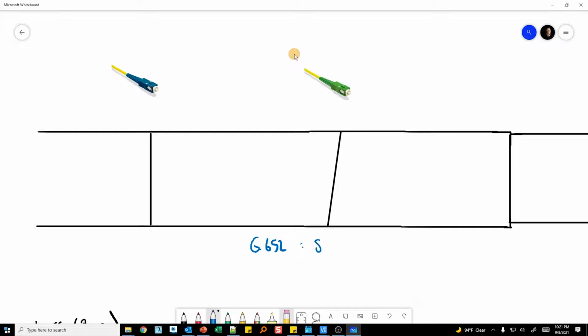So we're sitting at 8.3 microns, 8 to 10 microns or whatever for single mode fiber, depending on the type of glass you have. That's basically the core size. This is not exact, so I'd have to look up the specs. I think it's 8.3 microns. That might be the mode field diameter. You'll have to excuse me, I'll check on that and add a notation.